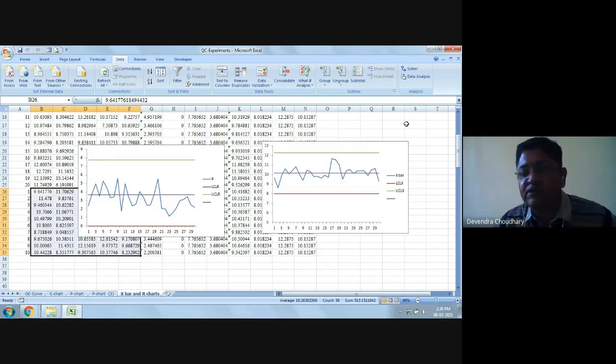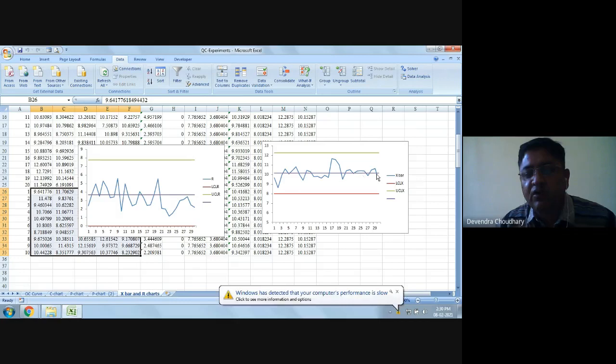Now, when we shift the variability, you see that if the variability decreases, then on our chart, the variability is depicted by both the R chart and the X bar chart. The points on the R chart will start falling below the center line, whereas on the X bar chart, the points will fall very near to the center line.